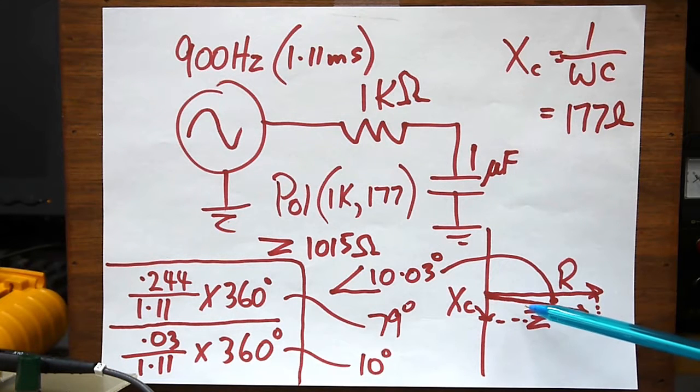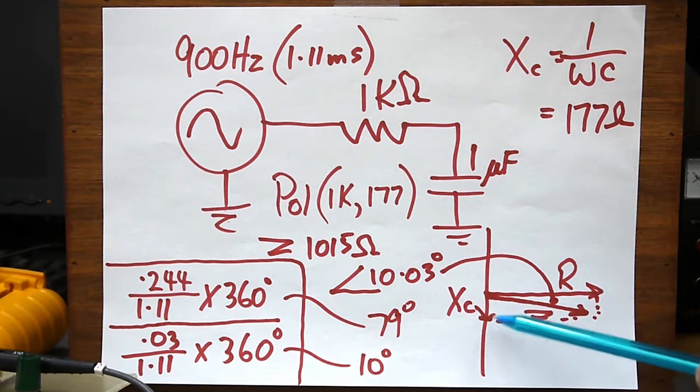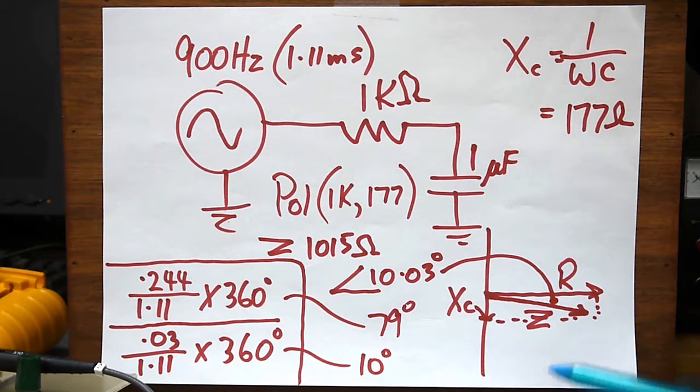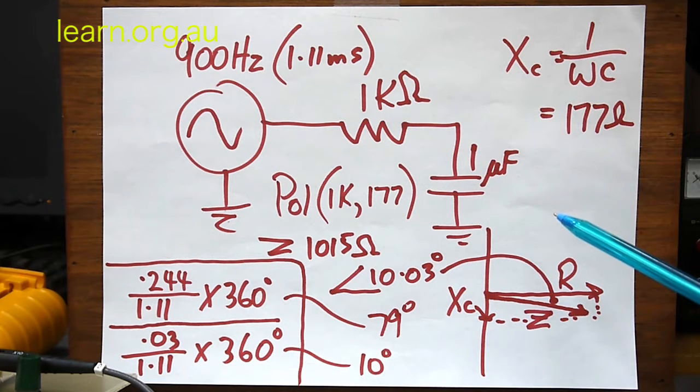And we've got, of course, 80 degrees in round terms between the supply voltage, which is leading the voltage across the capacitance in the circuit. So that pretty well wraps it up, and that's exactly in line with what we did in the theory in class using the circuit simulator. But in this case, it was using the Rigol oscilloscope and using actual components to do the job and prove that it all works out exactly in line with our theory.